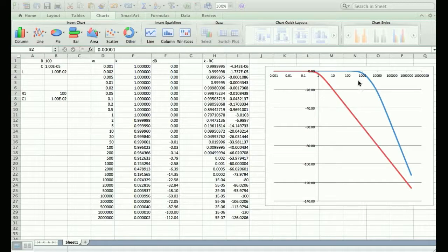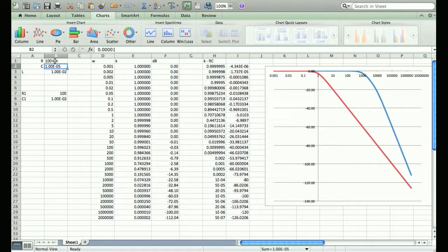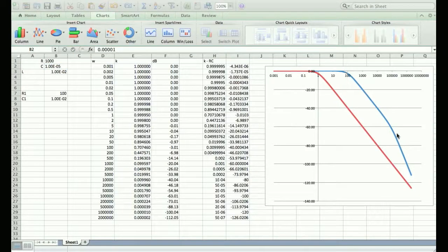When you have an RLC circuit, if it's completely imaginary, it falls off at 40 decibels per decade. But if it's overdamped and it's an RLC circuit, you can find where it's going to fall off at 20 dB per decade and 40 dB per decade by the roots of the characteristic equation. Those roots give you the exact frequencies where those kinks are that we saw earlier.